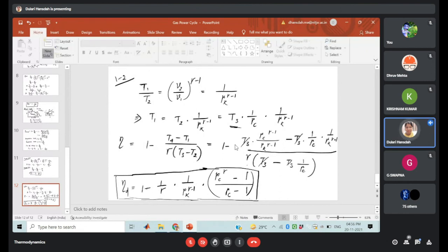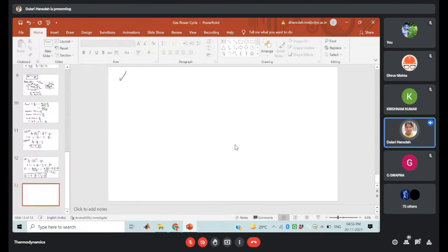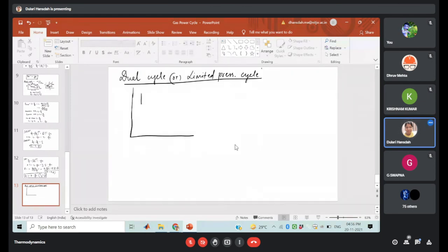ठीक है, नाउ आई विल डिस्कस द डुअल साइकिल, जो आल्सो नोन एज द लिमिटेड प्रेशर साइकिल है. Okay, so this cycle is applicable for the high-speed diesel engine. So in which both heat addition will be there. Both heat addition means in case of the constant pressure as well as the constant volume. Okay, both केस में आपका हीट एडिशन रहेगा और बाकी जो प्रोसेस है वो सेम रहेगी.